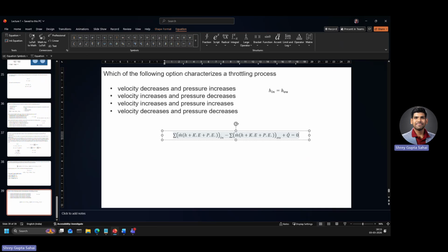So you might be tempted to say that this is an adiabatic process. It is not. In a loose sense, you can say it is an adiabatic process, but note that when we say adiabatic, isochoric, or isobaric processes, generally these are for constant mass processes, when you have control mass rather than control volumes.